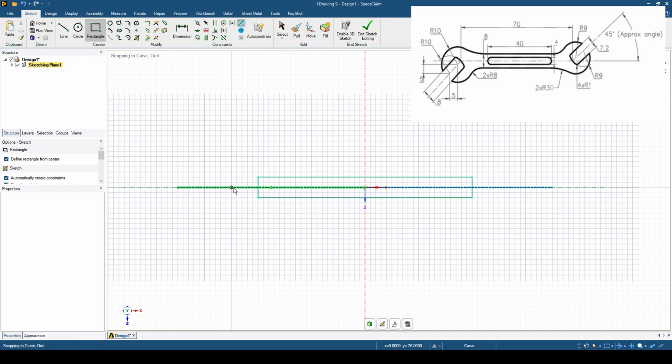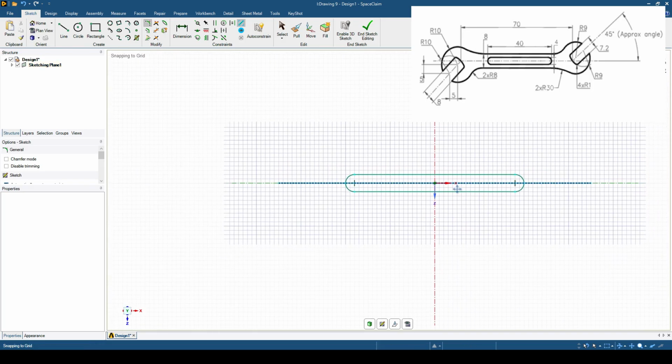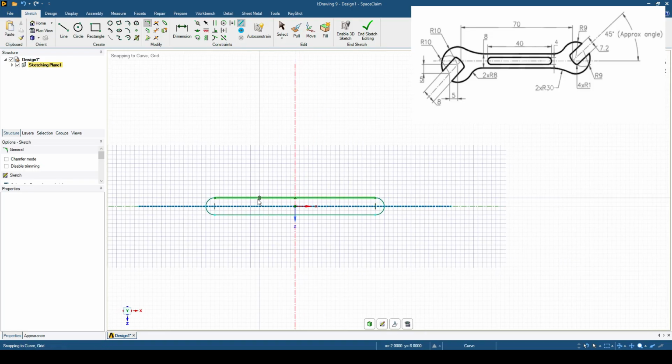After that, you can see that we have full corners. That means they should have a radius of 2 millimeters. So I'm going to choose the corner feature in ANSYS and choose one side, the other side on the right 2, and the same on the other side 2, the same there. So we are finished with this small oval form.